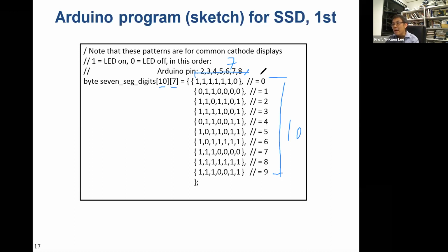So you define a matrix, and why do we need this kind of array? Because we can easily use it to assign 1 and 0 to turn on and turn off the LED, with this simple definition of an array. This provides a simple way to control the 7-segment display. This is something quite important. Once you have an array of LEDs, you need to think about how to do the simple control, how to write the program. Okay. Do you have any question about this particular one?